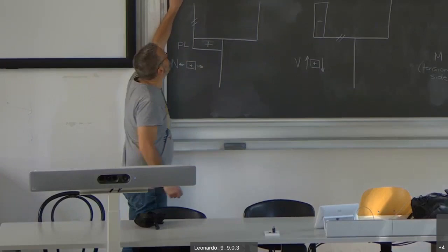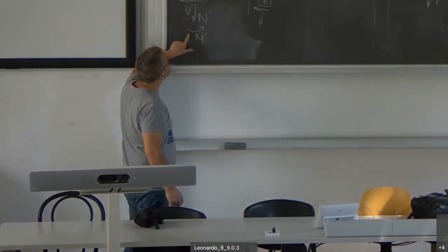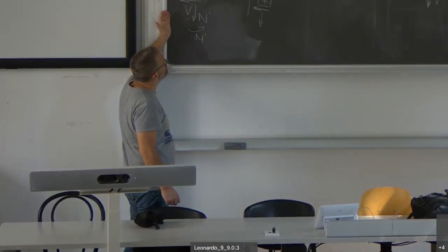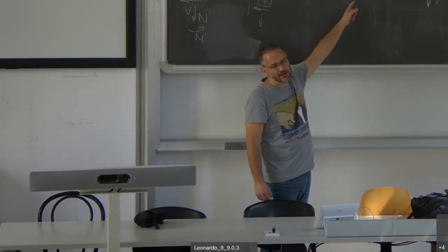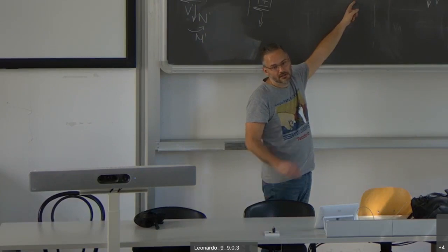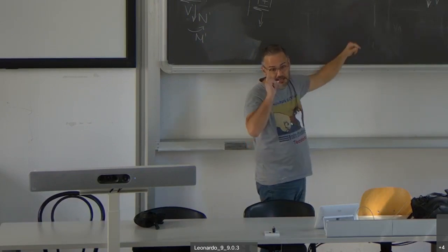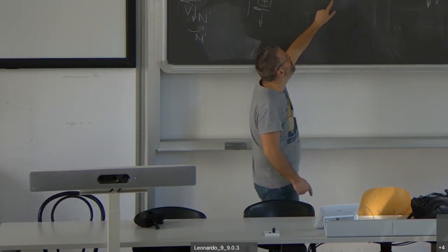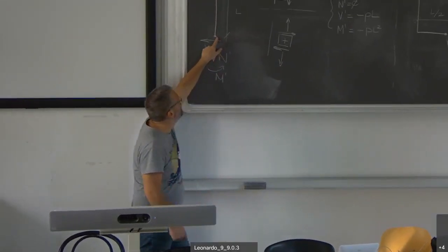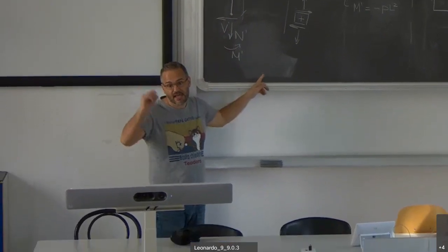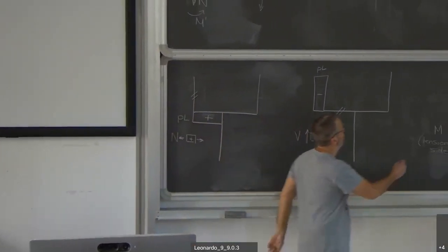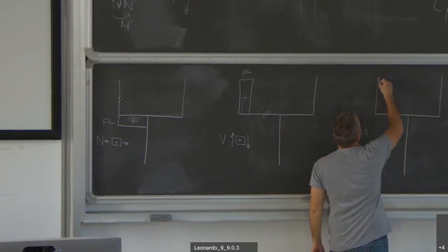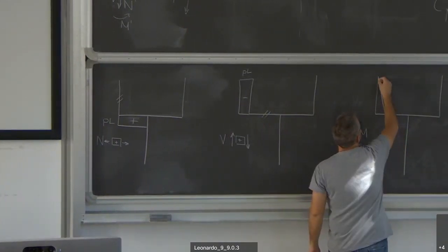Here, I assumed tension to be left. What I got is minus PL square. So tension is on the right. Note that this value only takes place at the bottom. At the top, since it's a free end, bending moment is 0. So what I have is like this. Straight line.